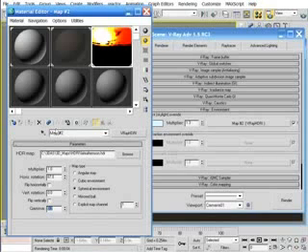Alright, well that does it for coverage of the HDRI within the material editor and the environment rollout within the render scene dialog box. Now let's look at another way to use HDRIs as environment lighting, and that would be with the VRay dome light. In this case, I've saved the best for last because using HDRIs with the VRay dome is preferred and a far better way of using HDRIs because of the better results that aren't possible with using an HDRI in the environment channel.